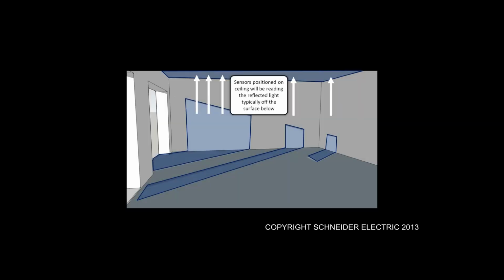Another thing you need to take into consideration is that, let's just say for example the sun's shining through a window, it lights up a particular area. That area could reflect more light into the actual sensor, and as a result could cause the sensor not to work as expected.